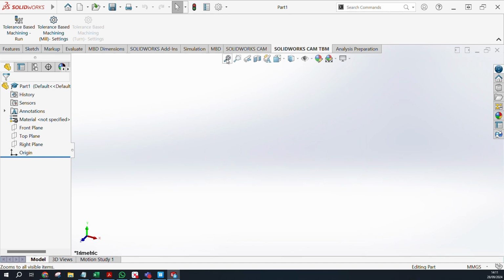And here, you will see that when you start your drawing, you are all the time zooming in and zooming out with your mouse wheel, so whenever your drawing gets a little dislocated from your screen, like it went to the right or to the left, I will show you during the work as well. You can select zoom to fit, and it will automatically bring your drawing right in the middle of your screen. And this is zoom to area, for when you want to zoom only one part of the screen, then just drag it and you can have it.